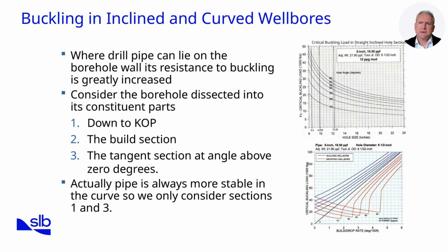The implications of buckling are severe, including higher torque and drag, casing wear, and the risk of stuck pipe. Therefore, engineers use predictive models and software to evaluate buckling loads under specific hole sizes, pipe weights, and mud systems.